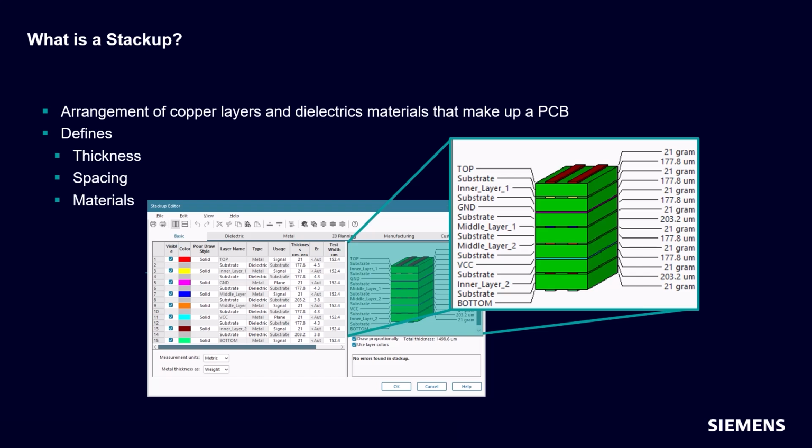It is important to clarify the term Stackup here in this context. A PCB stackup refers to the precise arrangement of metal layers and dielectric materials that constitute a printed circuit board. This layered structure defines critical electrical elements such as impedance and capacitance, and a stackup transmission line signifies a trace that's modeled directly within this defined PCB layer structure.